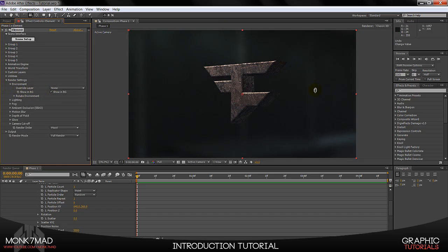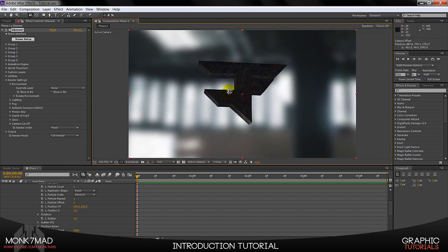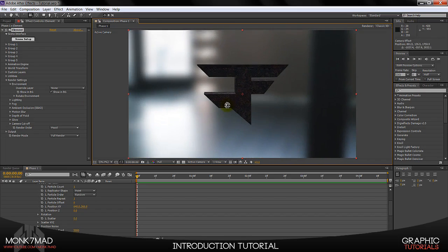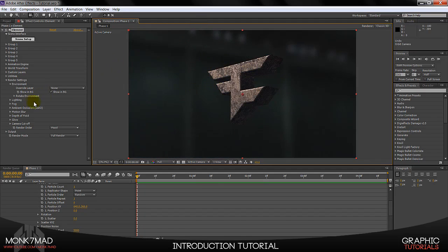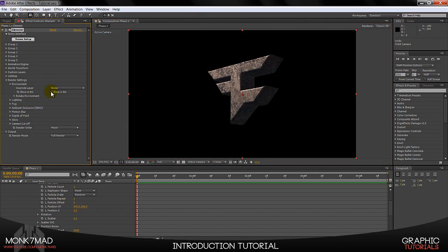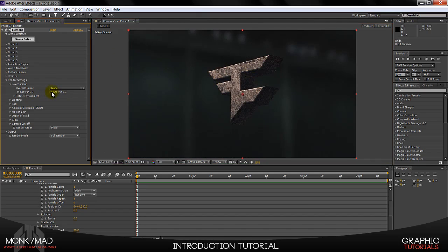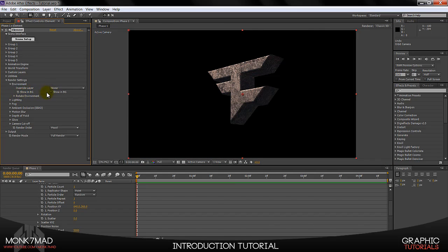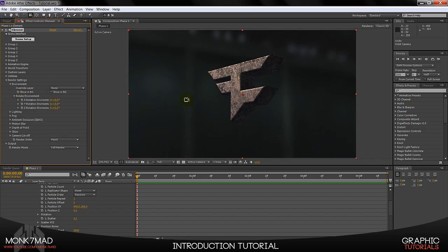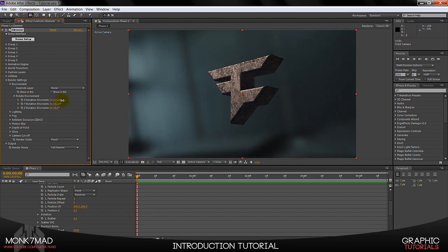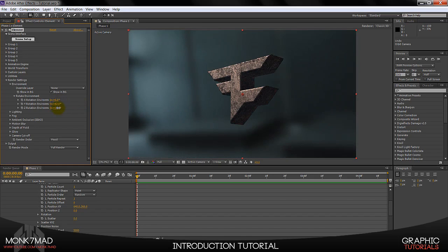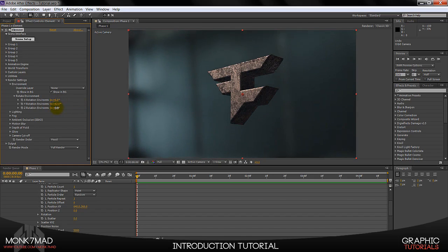So we've got our background, and I don't know about you, I think that's actually, so set back to the default one again. Oh no, actually I think it has kept the studio lighting there, which is good. You can choose to show the background or not via the tick here, and you can also rotate the environment to change the lighting source. So you mostly probably want to change it via the y-axis, but you can also sort of muck around with all of the other options available to you.